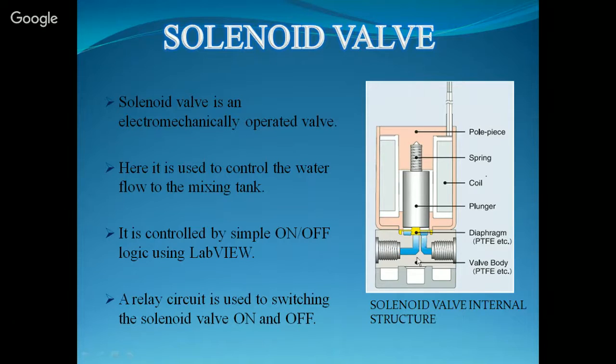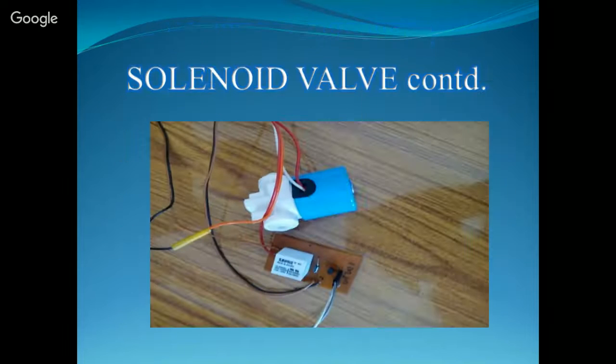In our application, solenoid valve is used to control the flow of water to the mixing tank. It is controlled by using simple on-off logic using LabVIEW. Here we have used a 24-volt solenoid valve with a relay circuit.